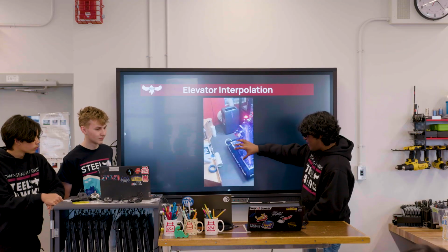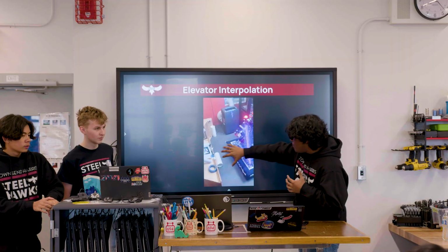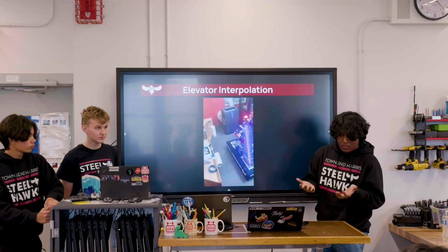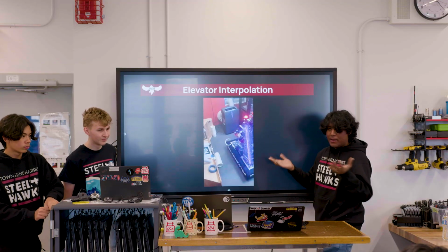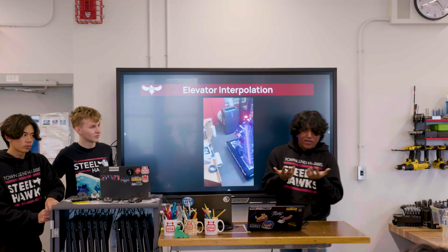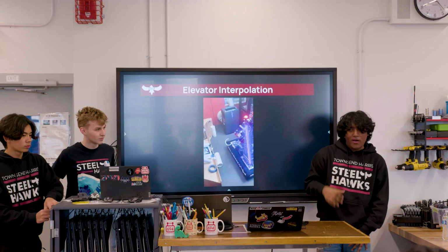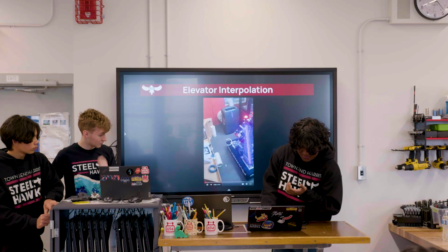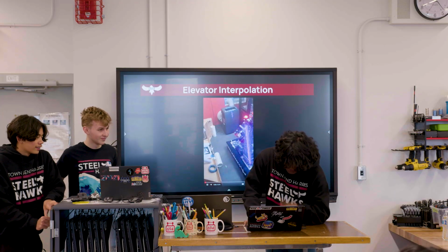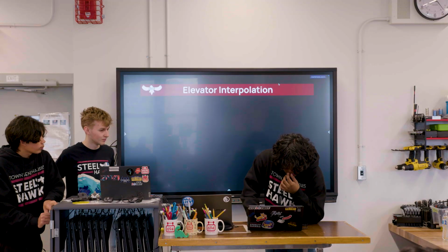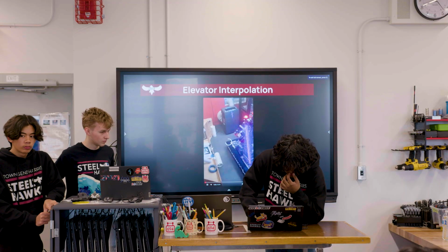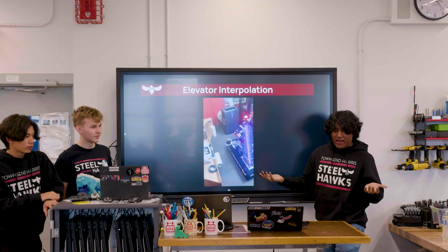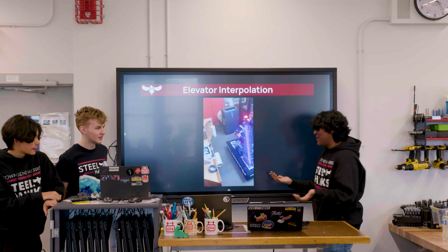If your constant setpoint relies on you being flush against the reef, but now you have an obstacle in the way where it's not possible to be in that position, you either waste 2-3 seconds of your cycle spinning the robot or moving the coral away, or you're able to use this solution, where it will just compensate with the height and you're able to shoot. I really want to show you the video so you understand what's happening.